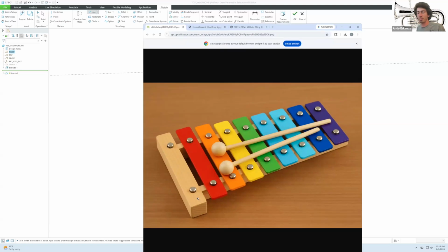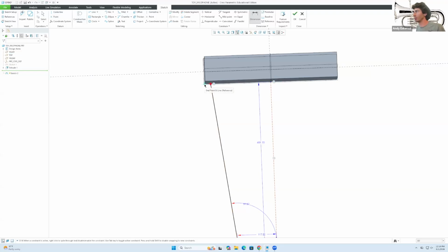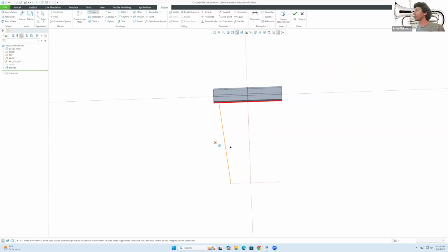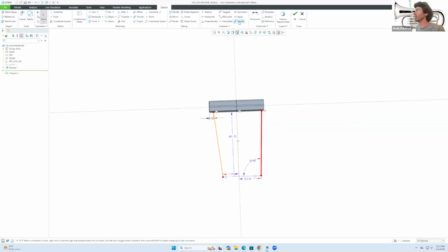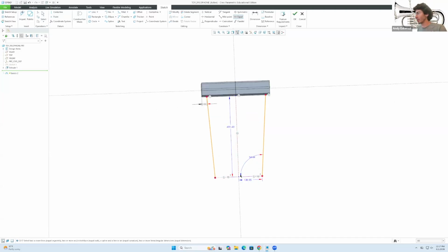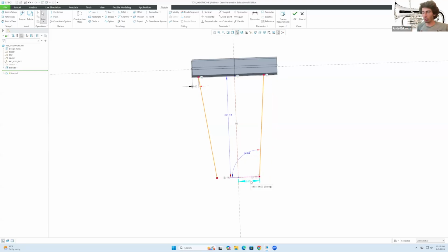So to look in there, we can give this some height. Or also I can say, right, I want the distance between here to be 30. Good. And we'll need that too. I'm going to draw a line here. Another line there. By the way, this is where we can start to use the constraints, because I can say are equal. I'll select those two, and you see that now those two lines are equal. Hence, if I modify this parameter, let me escape. Now, if I modify that and I make that 100, you see it automatically changes all of that stuff.